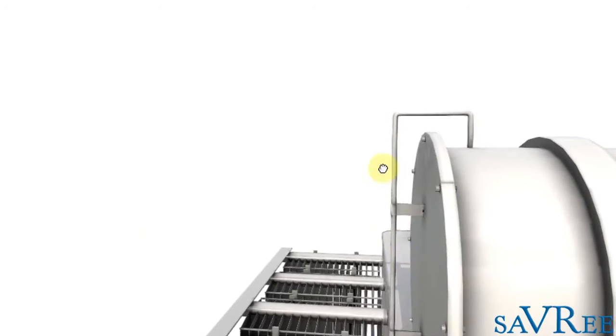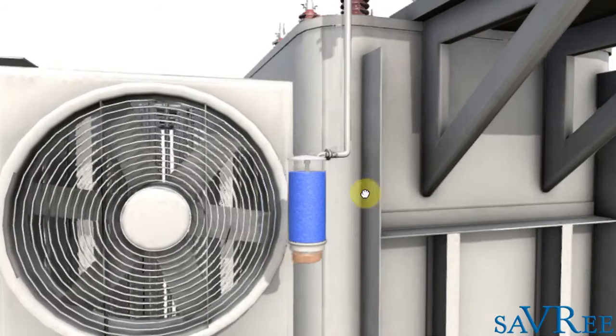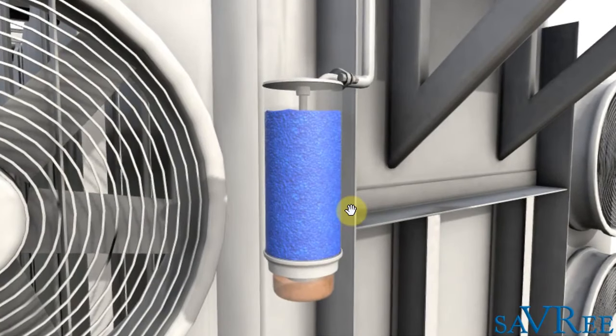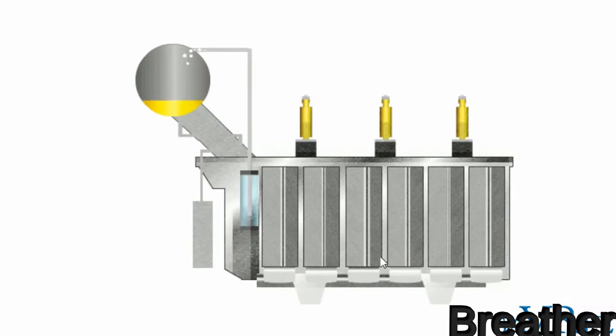Breather. It is attached to the conservator tank and contains silica gel, which prevents moist air from entering the tank during contraction of oil. It prevents transformer oil from moisture contamination. When the transformer temperature increases, the liquid expands and pushes the air out of the conservator tank and out through the breather.